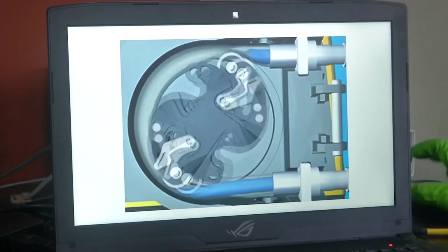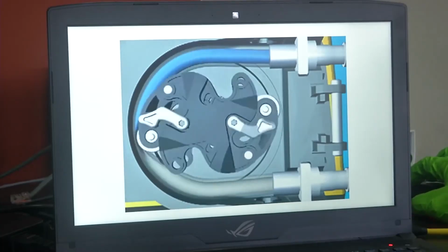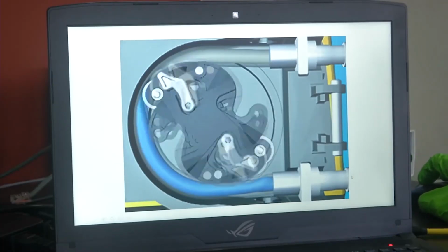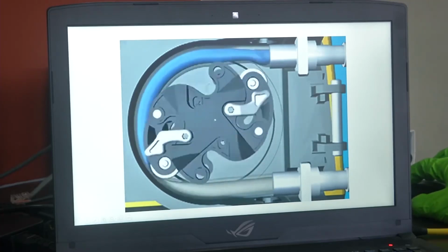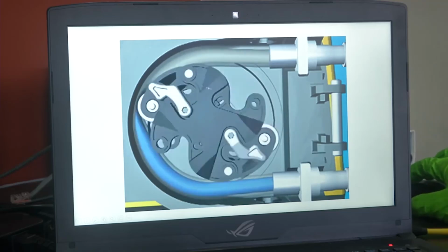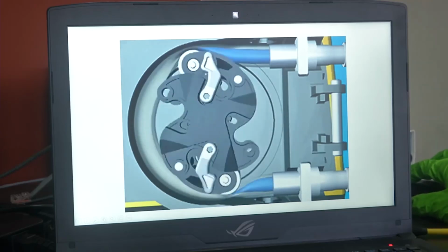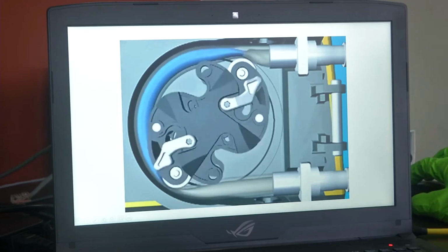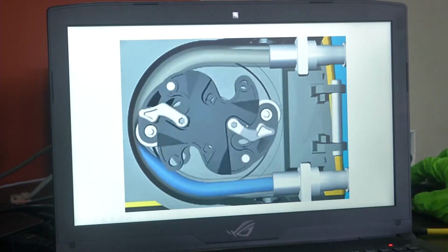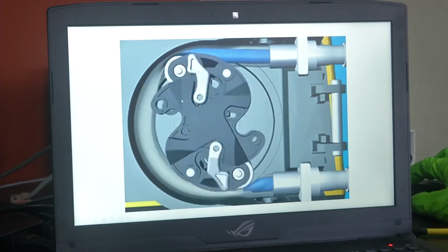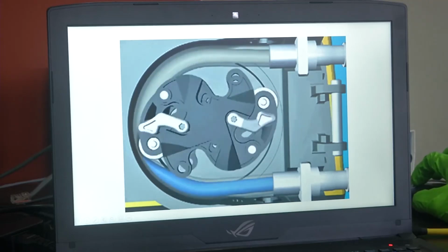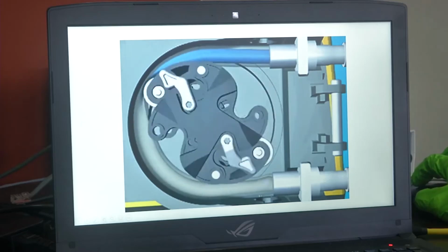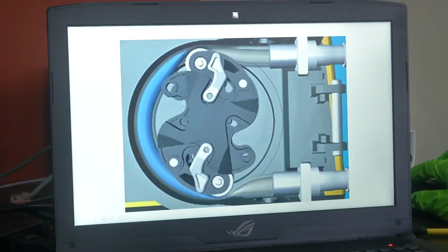You can see here in a GIF image that the fluid will come through this port. So, it will come over here. What we have is a rotating roller, and in that rotating roller itself we have some small wide rollers also, you can see. So, what happens is, this is the casing of the peristaltic pump, and there is a flexible tube over here.